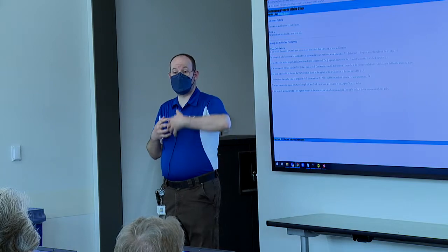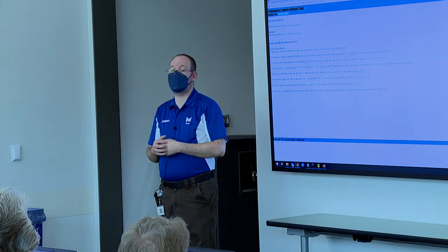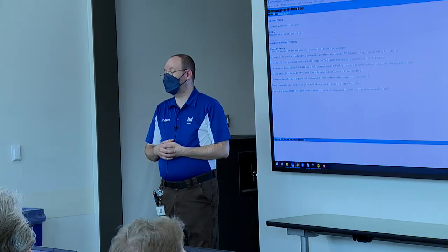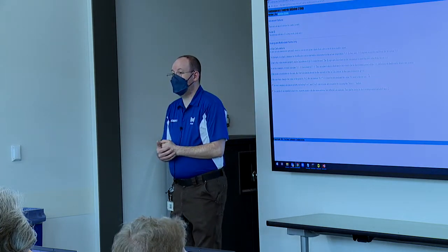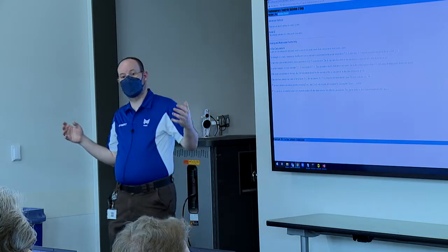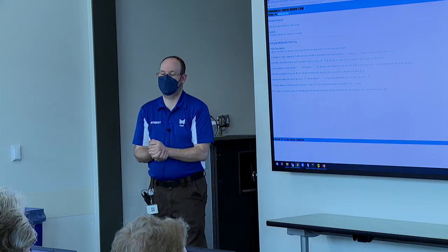You know how we discovered our controllers? Modbus doesn't have that functionality. You have to know the addresses of the controllers and manually add them. You have to go in and manually add every point in Modbus. You have to understand how Modbus registries work, which is a topic. We'll leave it at that.